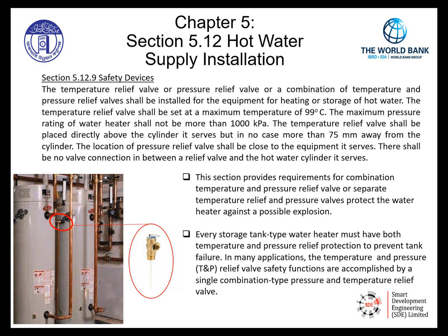5.12.9 contains safety device requirements regarding our hot water source. The temperature relief valve or pressure relief valve, or a combination of temperature and pressure relief valves, shall be installed for the equipment for heating or storage of hot water. The temperature relief valve shall be set at a maximum temperature of 99 degrees Celsius. The maximum pressure rating of the water heater shall not be more than 1000 kPa.